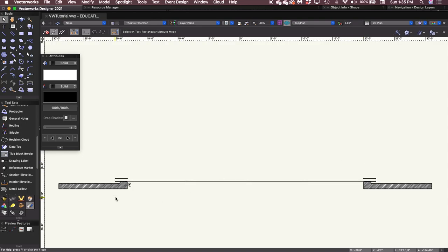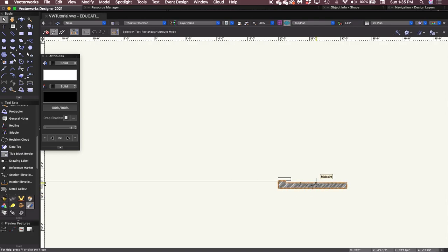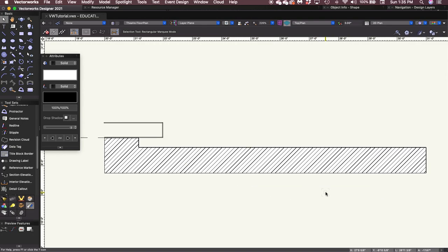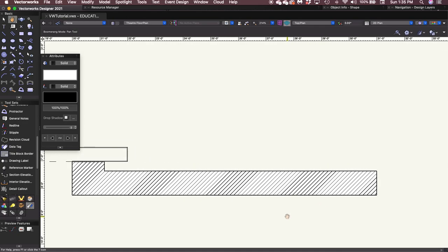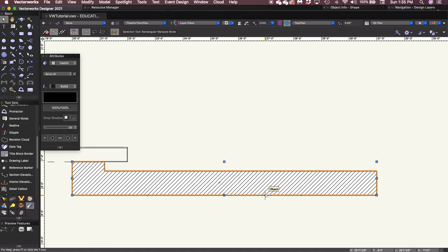In the previous section, we created the stage right proscenium, we mirrored it, and we moved it over 38 feet to create our opening. But now this needs to be a little bit bigger to represent the additional space that this theater is going to have on the stage left side. So I'm going to zoom into it here, and I'm going to select the polygon that creates our proscenium opening,